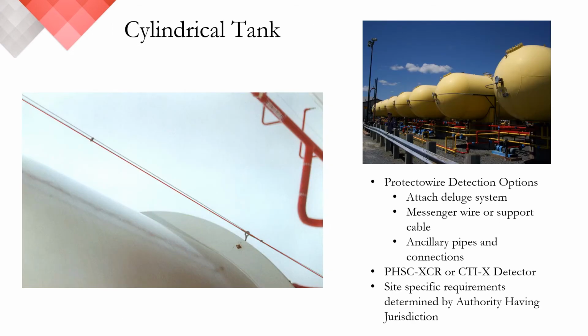So here's a nice slide depicting cylindrical tanks. You can see that there's a nice picture of Protectowire attached with double loop straps to a messenger wire, which is connected to the tank via eye-bolt. And the key to installing Protectowire is to not stress it out. This is a really nice installation. And remember, Protectowire is amazing, but we're only as good as we're installed. And I cannot stress that enough.